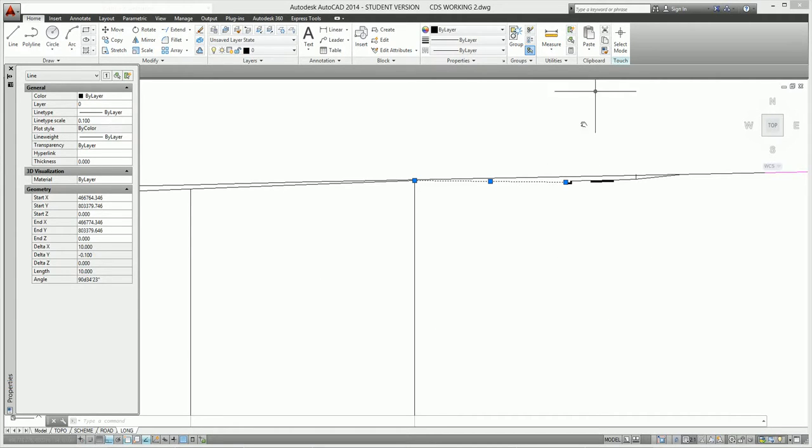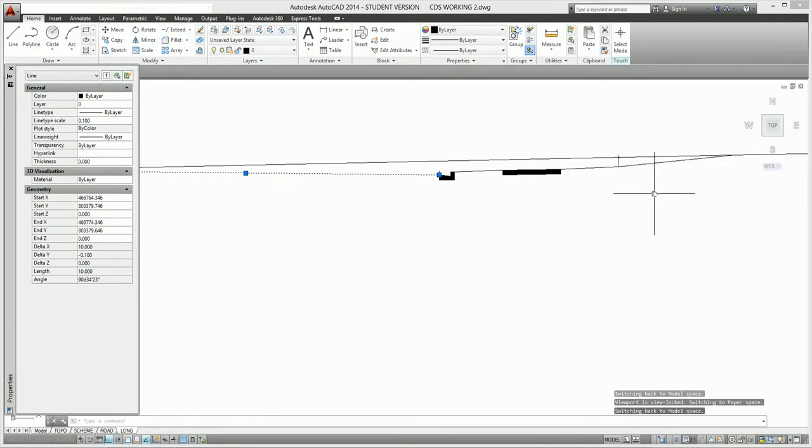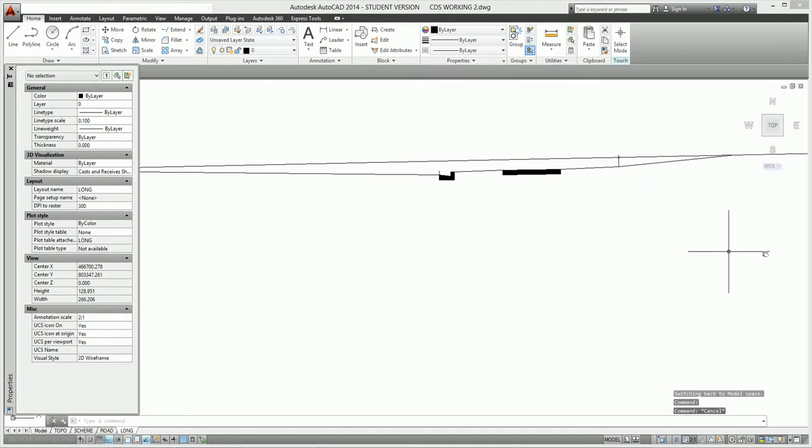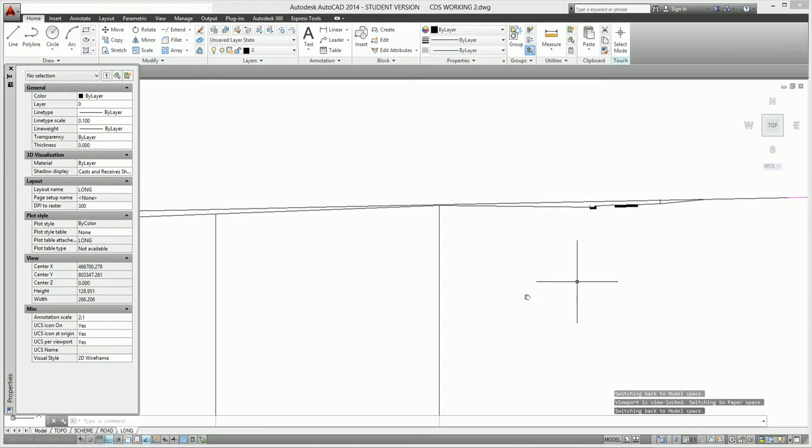We don't have to bring our stormwater reticulation quite as far. That's further down the track. And then I've also come through to the boundary, and I've shown here my cut or fill back to meet into the existing surface, and I've got that at 1 in 10, or a 10% grade, which is sufficient: not too steep, but not too flat, and that's where things will cut back into the existing surface.